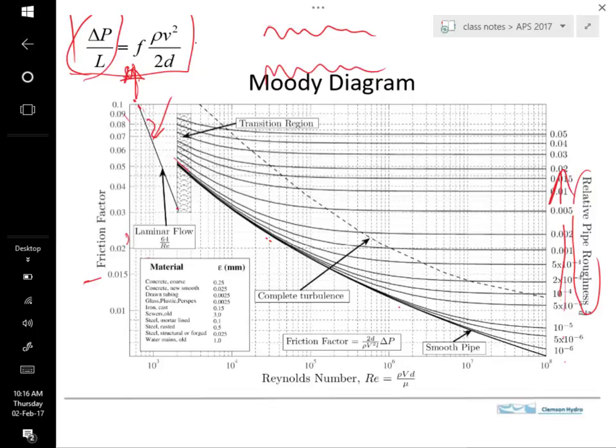But then look out here. Here, the friction factor is just a constant value. It's not related to the velocity, and it has a constant value. And in this case, out here where the slope is unchanging, the head drop will be proportional to the velocity squared.